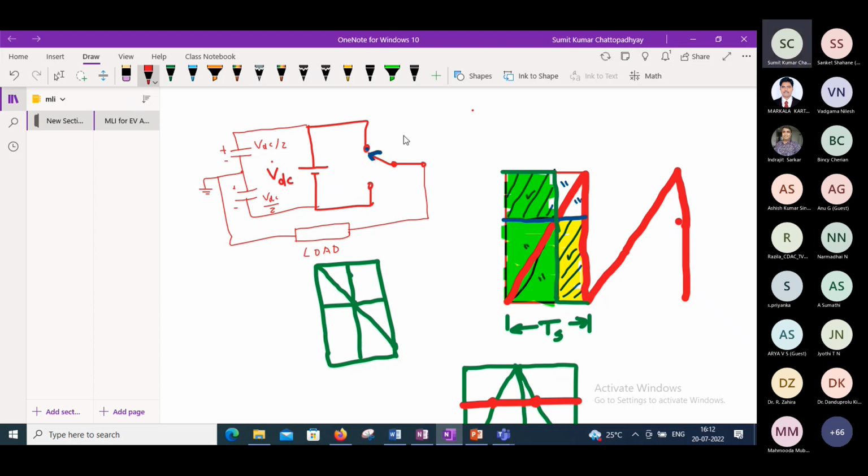Now, with this, if we go for high frequency, of course, the output voltage can be close to sinusoidal. Lower order harmonics will not be there. Higher order harmonics will be there, which can be easily filtered out because of the coupling inductance or filter. If we have an inductive filter here, or some inductance in the filter, we know the impedance of the filter is omega L.